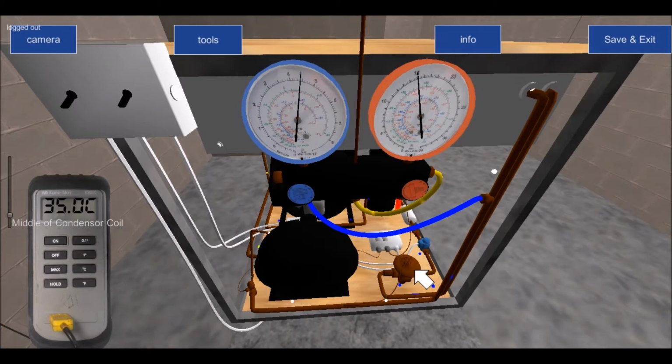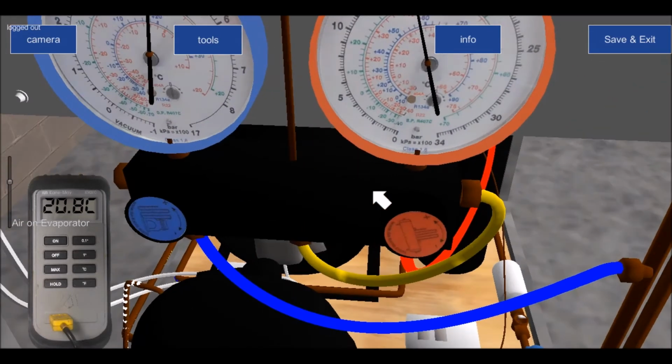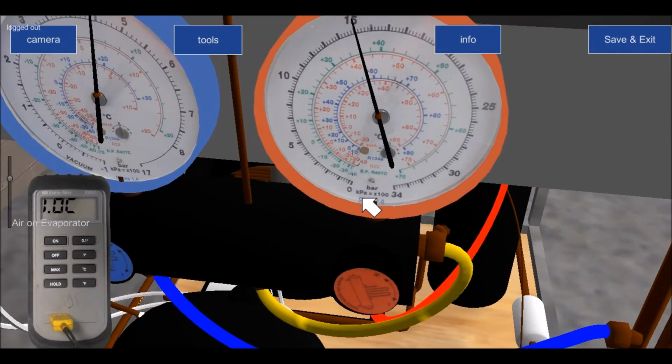And every system out there must have that label with that minimum amount of information in it. But anyway, getting back to this exercise, we then systematically go through these refrigerants and we see which one of these refrigerants, if I slide down along here, gives me 35 degrees.